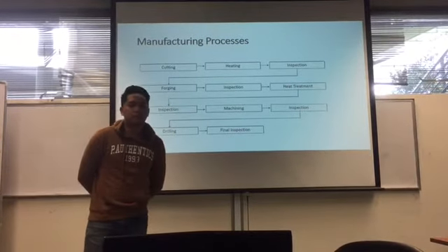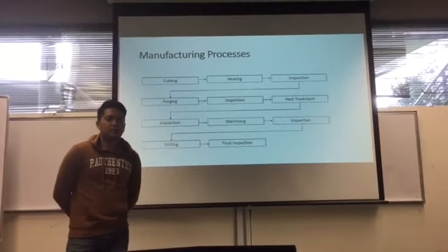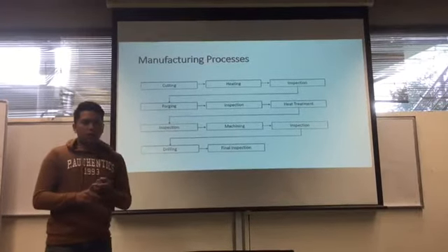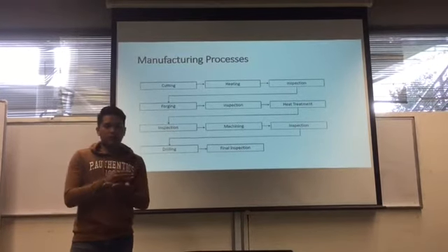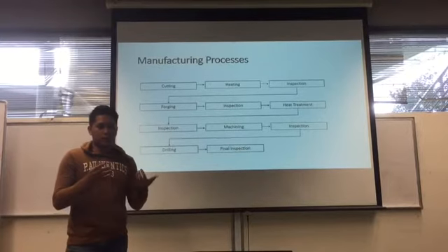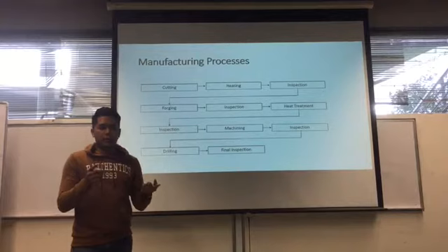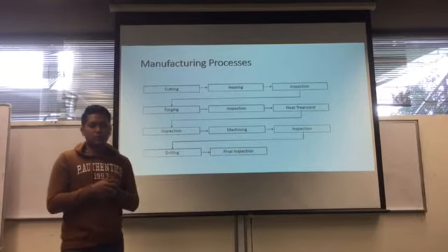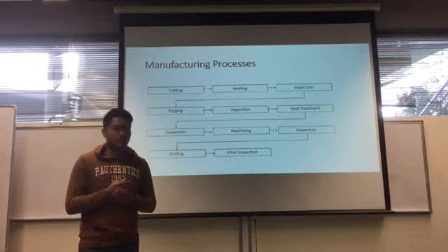Okay, the first process, which is cutting, consists of two methods, which are cutting the round plate and also cutting the stripes. It starts with cutting the stripes from the metal plate, which is then rolled into the round shape. Next, we will cut the stripe into a round plate with the spec that was given in the procedure, based on the inner diameter, outer diameter, and also the thickness.